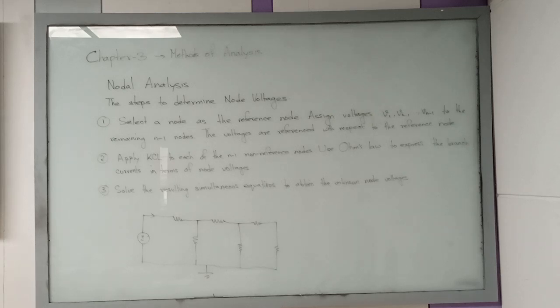The first step is to select the reference node. Basically we select the reference node by considering the ground point.